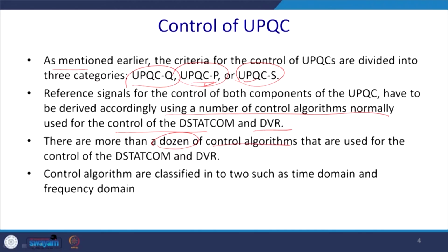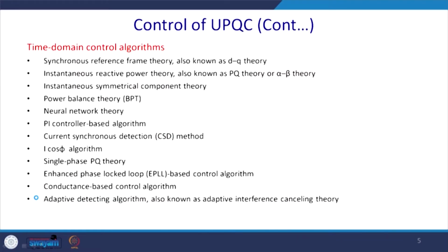The control algorithms are classified mostly in two domains: one is in the time domain, another is in the frequency domain. These are the dominating features of the time domain algorithm. One is synchronous reference frame theory, also known as the DQ theory. It is quite popular, and this strategy we will discuss in tandem with the grid connected voltage source converter.